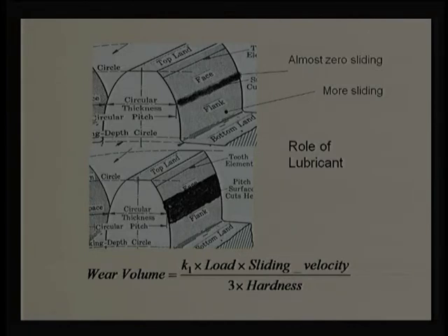So, again when we do the friction analysis, we find there will be change, and if there is wear of the gear, even though we keep a high contact ratio initially, it is going to decrease with time. It is not going to be constant. This contact ratio depends on the time duration. If there is more wear, surfaces are getting damaged, then the contact ratio will decrease. So, in other words, we say that a gear will never have infinite life. It will have only finite life, whether it is 20,000 hours, 30,000 hours, 40,000 hours.